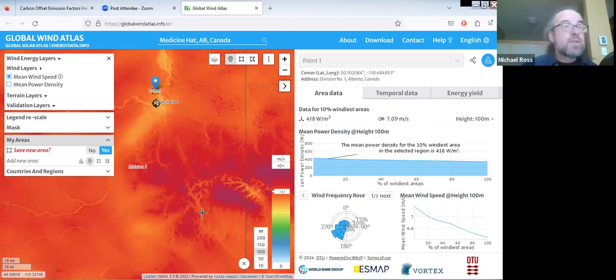So I'm going to pick one of those areas. And of course, in the real world, you can't be very casual about picking these areas. You have to see what the land use is. So for instance, there is a park in this area, and you're not going to typically be putting wind turbines in parks. You'd have to look at your proximity to transmission facilities for transmitting power. You might look at whether there's cottages in the area, whether there's migrating bird or bat populations in the area, or they're going to be coming through. So those are all real world considerations that I'm ignoring.